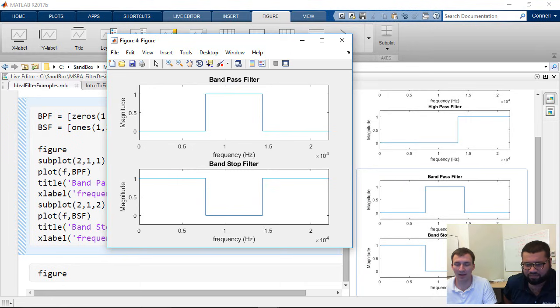The purpose of the bandpass filter is to preserve frequency components within a specific frequency range. Okay. And then conversely, the bandstop filter attenuates frequency components within a specific range. Okay. So these are all pretty simple, but pretty common filters in digital signal processing, right? Correct. These are considered ideal filters. So typically when we have ideal filters, they're not the best choice for application. They're more for analysis and theory.